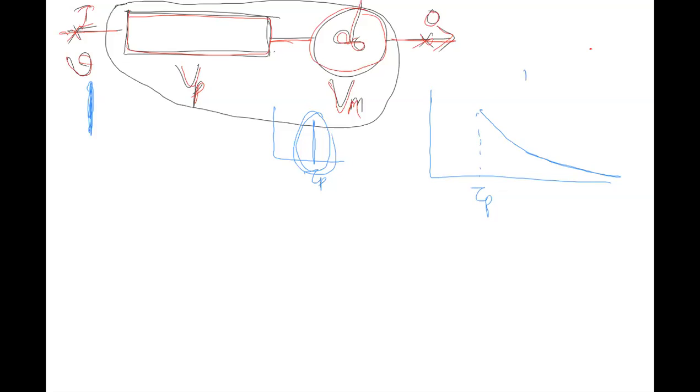Then what happens to the equation? 1 by tau m e power minus t by tau m is your RTD of CSTR, no? But your input is delayed by tau p minutes. So t minus tau p is the equation. Your time is just replaced by t minus tau p.